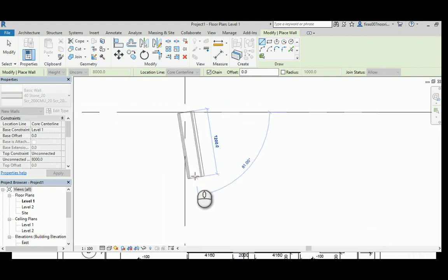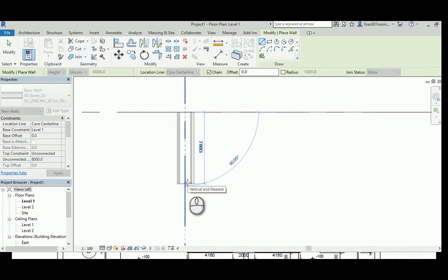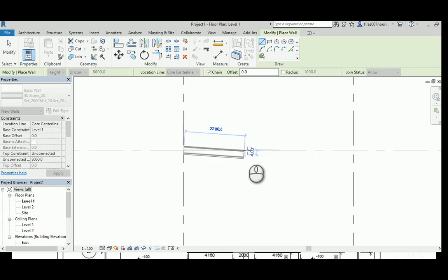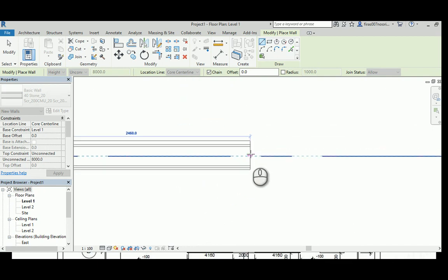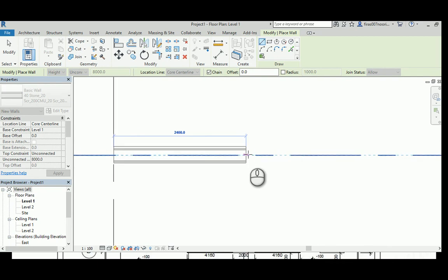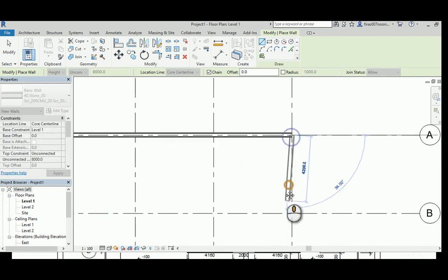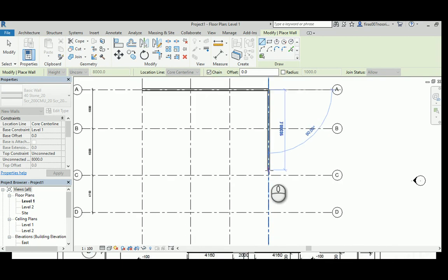And if you click downward or you go counterclockwise, you're gonna see that the wall is flipped, so you just hit space, you know, like it's gonna go correctly, or that way. Now you should have flipped, you know, like with hitting one space as I'm doing now. So be careful when you place the material, not to place the exterior finishes to the inside part of the whole thing.